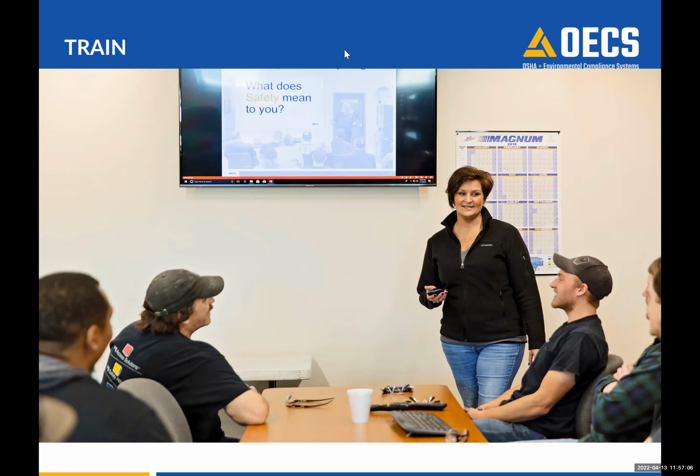David asks, can we use extension cords for floor fans during the summer months? Sure, you can. Go ahead. When would this be considered an OSHA violation, if at all? The only time it would be an issue is if it's creating a trip hazard, so you're running across the aisleway, or if there's damage to the cord.